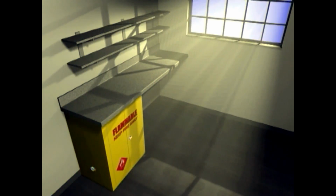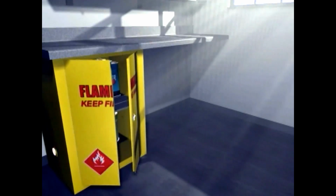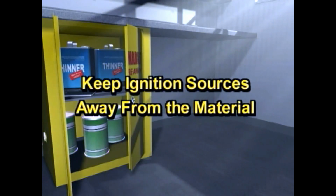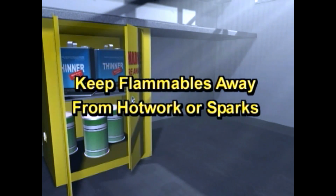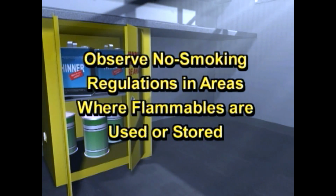Flammable materials also require special precautions. Here are some rules for handling flammables. Carry glass bottles containing flammable liquids in a rubber cradle to reduce the risk of breakage. Keep ignition sources away from the material. Use static bonding and grounding procedures when transferring flammables. Keep flammables away from hot work or sparks. And observe no smoking regulations in areas where flammables are used or stored.